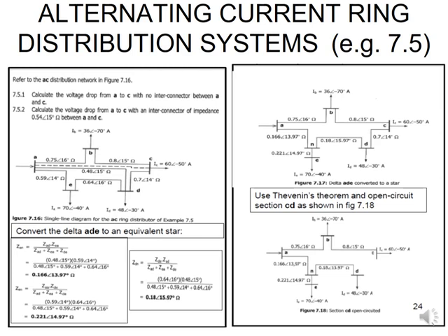Now, when we go to the questions, they ask us to calculate the voltage drop between A and C, both with the interconnector and without the interconnector. So we're going to start without the interconnector. Remove the interconnector, and you're still going to have that line between A and D. Because of that line between A and D, and then E and back to A, you have a delta circuit.